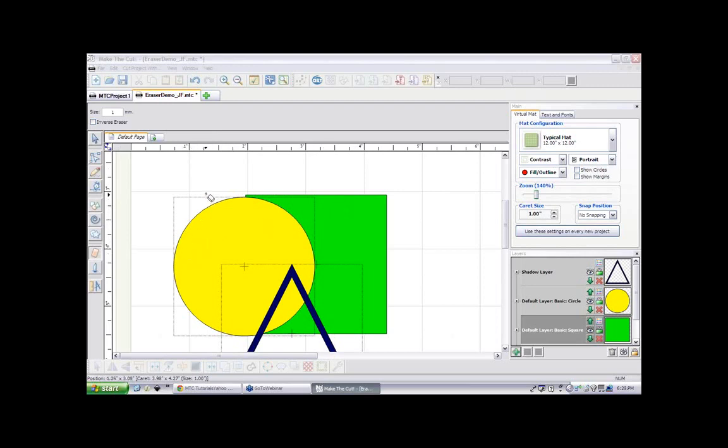If you just have a single shape, you can just use your mouse and draw an irregular shape, and it will just remove the color like you would expect it to. If you wanted it to be a straight line, I'll use Control-Z to undo that. If you wanted it to be a straight line to erase, which I use very frequently, you press the Control key, then you click the mouse, and you drag, and wherever you release is where that line will be.